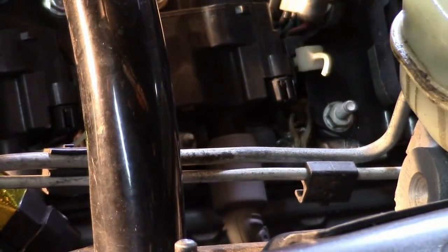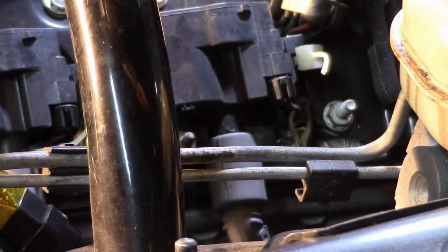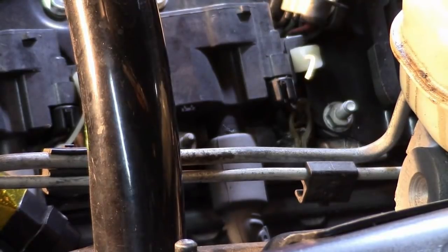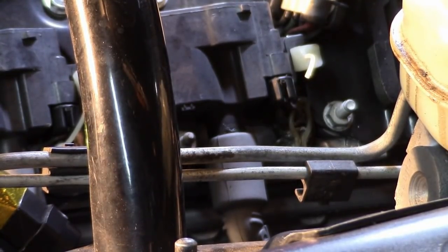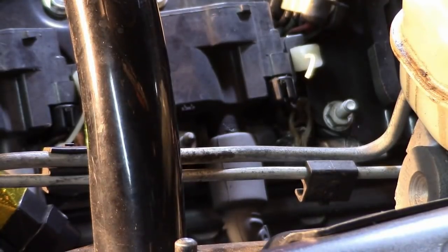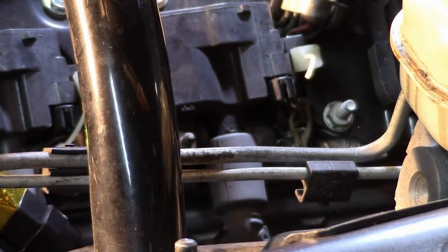One really big advantage with something like this is, in this case, it's not applicable because all our coils are readily available. But as you know, on many designs, you've got at least half of the coils, if not all of them, under the intake manifold. So, of course, your 98%er is going to have to pull the intake manifold off to replace things. And they're probably not even going to test it anyway.